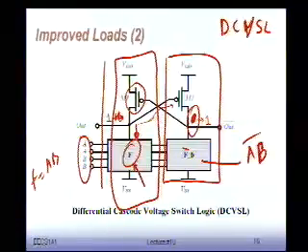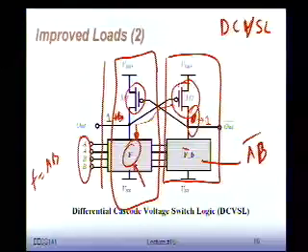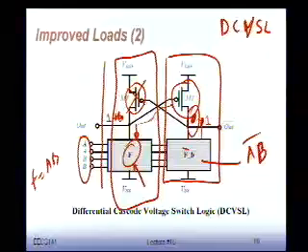The PMOS and the NMOS network trying to pull it down, just like we had in pseudo NMOS. So we're starting to pull this down, but by doing so, we start slowly but surely turning on this PMOS. That's the feedback effect. We bring this down, this PMOS is going to go off. We start pulling those nodes up high. Slowly but surely we're turning off this PMOS. And suddenly this goes high and the whole thing flips around from one side to the other side.